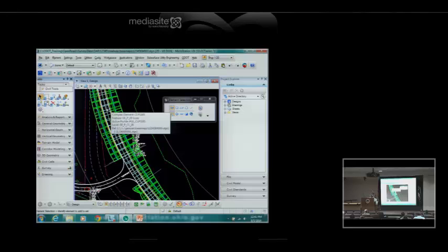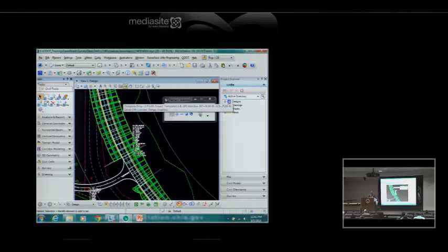And I've dropped in a template, and I've run the template up to my intersection, and then here I've dropped in a different template that doesn't have the side slope information, and I've picked up here and finished running the template throughout. So that's what these graphics are from the template drops and the corridor model itself. That's kind of what the stuff looks like in 2D.